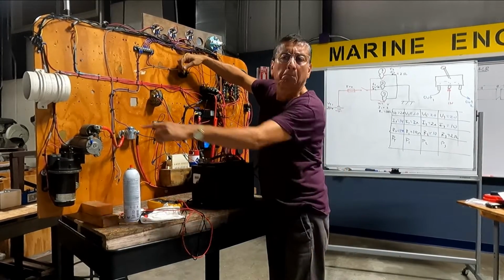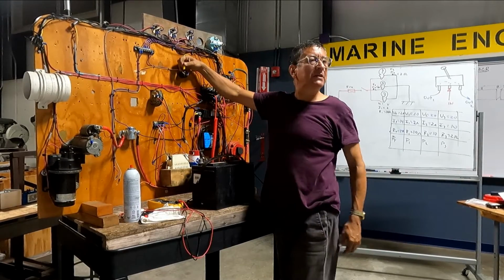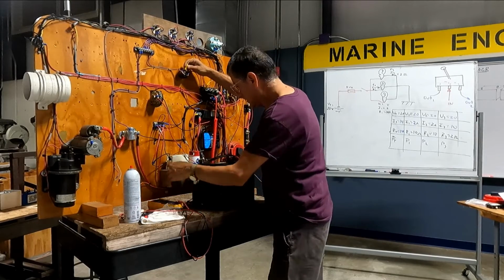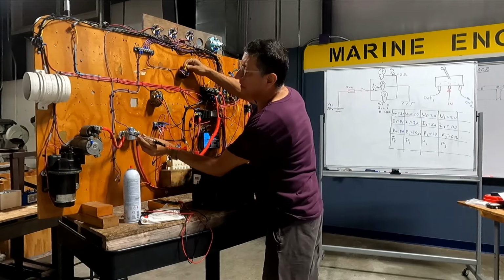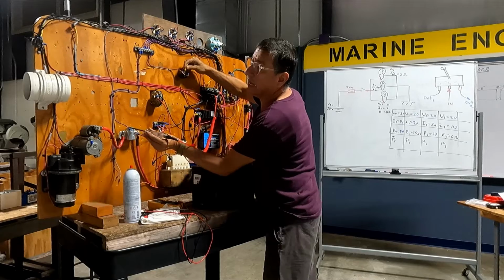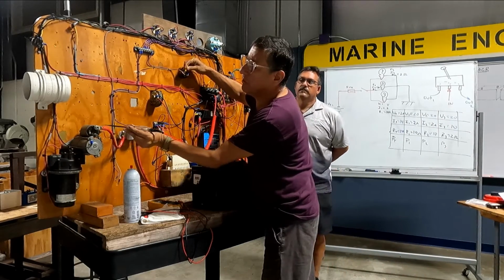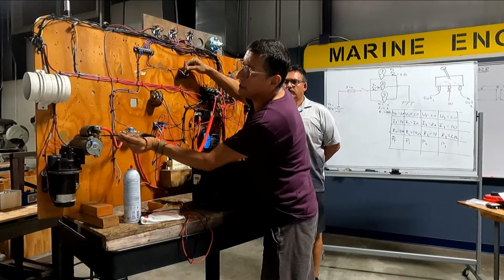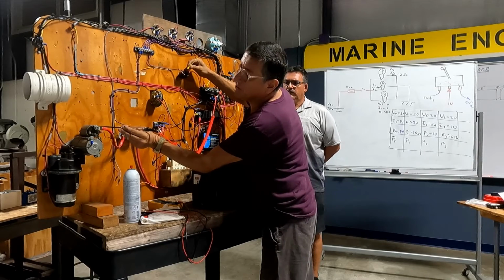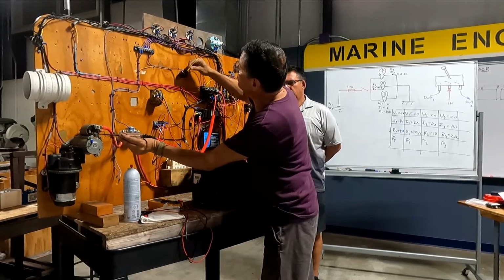In the second one, nothing. Probably that element is damaged. Let me check if I have power here when I bring power here. At this moment, I don't have power here. When I bring power to ignition, okay, I have power in the big one. And when I have power here, I have power here. To pass the power from here to here, I need signal in the yellow red, no? Okay, let me bring signal to the yellow red.